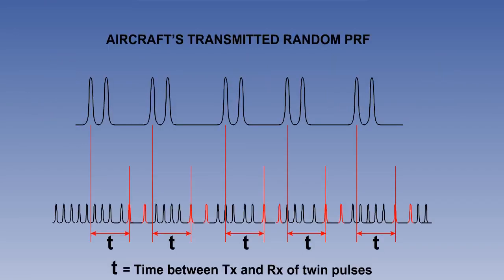When a ground station, the transponder, receives an interrogation pulse, it sets up gates to match the random pulse repetition frequency of the transmitted twin pulses. Electronic gates essentially blank out signals with other patterns. The responses on the transponder's carrier frequency include an individual aircraft's paired pulses plus those from other aircraft. The receiving equipment of an aircraft is designed so that only the responses which match its PRF are allowed through the gates. The pulses have now achieved lock-on, and the DME leaves search mode and enters tracking mode.